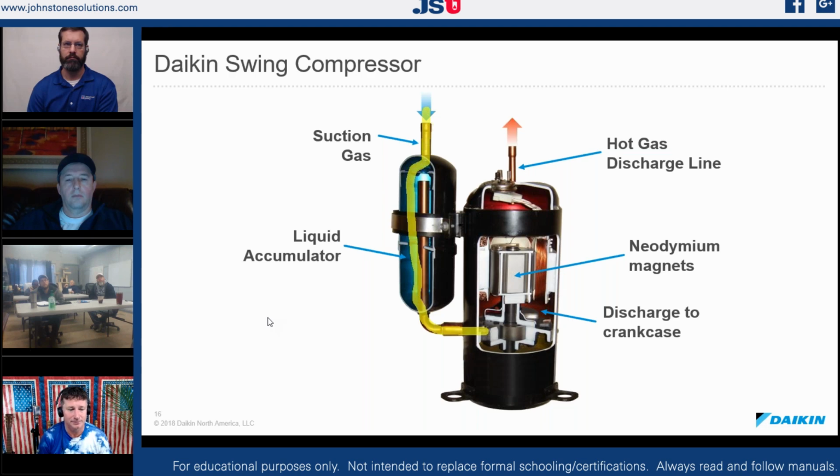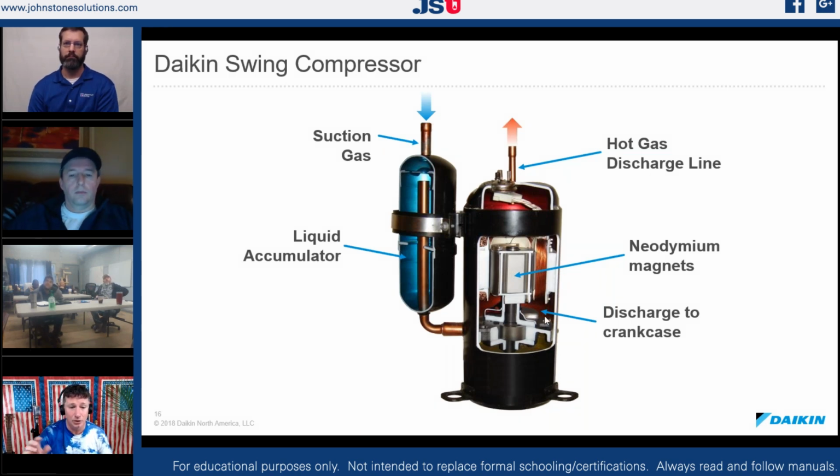He calls me 45 minutes later. He made a trip over to one of our ND East locations, comes back. He says, man, I got back here and turned that thing on and it fired right up. Everything's running perfectly. I was like, yeah. So our oil finally had a chance to migrate back into the compressor. He's like, who'd have ever thought? I said, well, a lot of us didn't actually think about that. It was something that we just found by doing these classes and talking to people and looking at how things are constructed. So understanding how something is constructed is a tremendous asset in our industry.